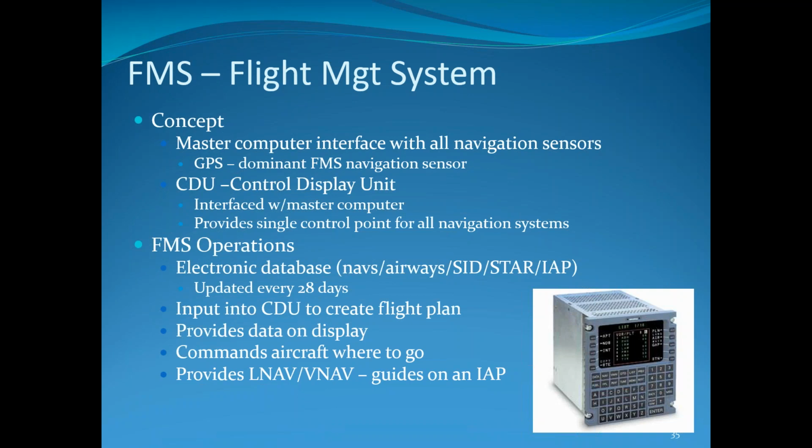So whether you're using RNAV, GPS, or even VOR, DME, any of that stuff, it is all controlled and read by this FMS. It's taking literally anything you can think of in navigation, whether it's satellite navigation or ground-based navigation, and it all runs through the FMS. The FMS takes all of that information and puts on one display what it's using, where it's located, and on your flight path, it calculates everything for you.